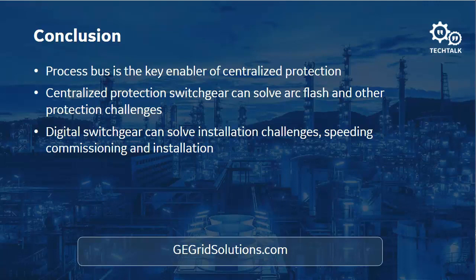Can the merging units have current and voltage displays? That's a fascinating question. It gets into a philosophical problem for me. Our merging units do not have current and voltage displays. They don't have them. Philosophically, I would think that we should not have displays on the merging units, because that display would really only be used during commissioning, and it would cost us money.